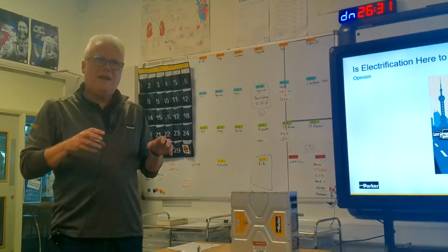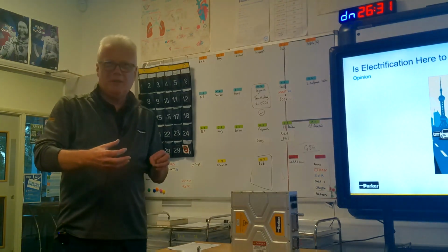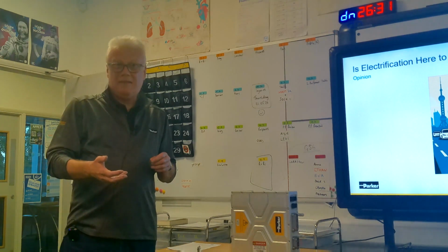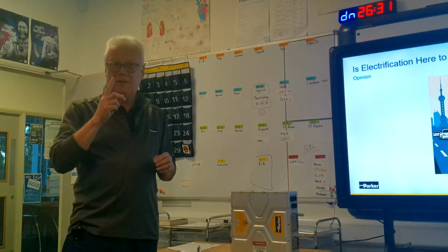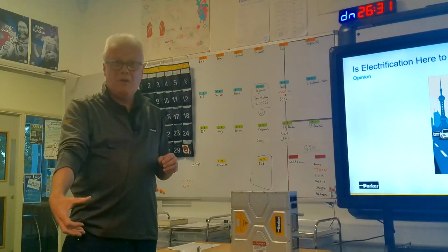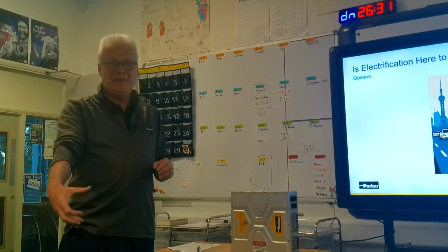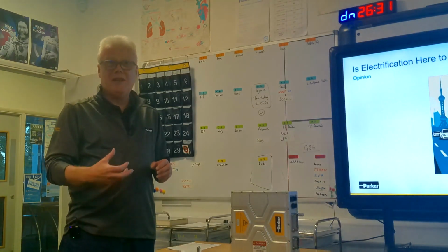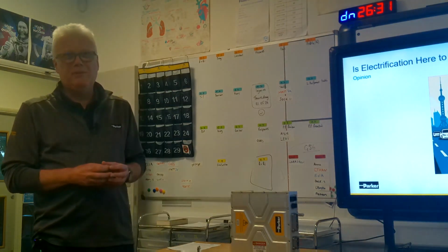There are people out there that want to put motors in wheels. Probably not a good idea to put your power electronics in wheels, but motors on wheels. But think about that. If I had a fault in one of those motors on one of those wheels, I've suddenly got a seized wheel on one corner of my vehicle and I'm going at speed. That's not a good position to be in. That's why most vehicle manufacturers like the transaxle thing, because it gets rid of that problem.